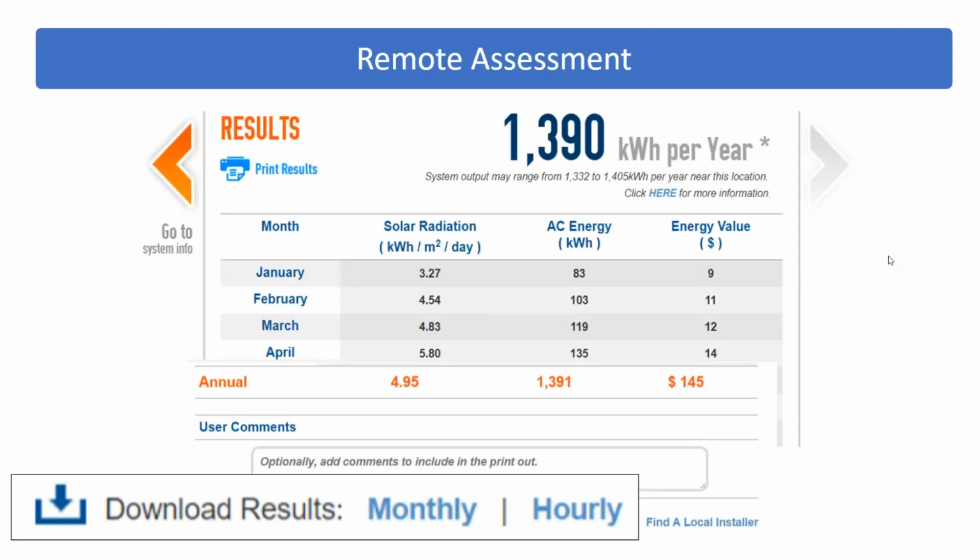What would a north-facing array do? Well, a north-facing array would really only be producing its electricity in the summertime. And maybe if I'm up in Minnesota, I don't really care about my summertime electric bill. I'm not running the air conditioner. But if I'm down in Texas, that's when I'm running my air conditioner. So that additional power boost in the summertime on the north side of the roof, in Texas, it can make sense. Whereas in Minnesota, you'd have to use a little bit of common sense.